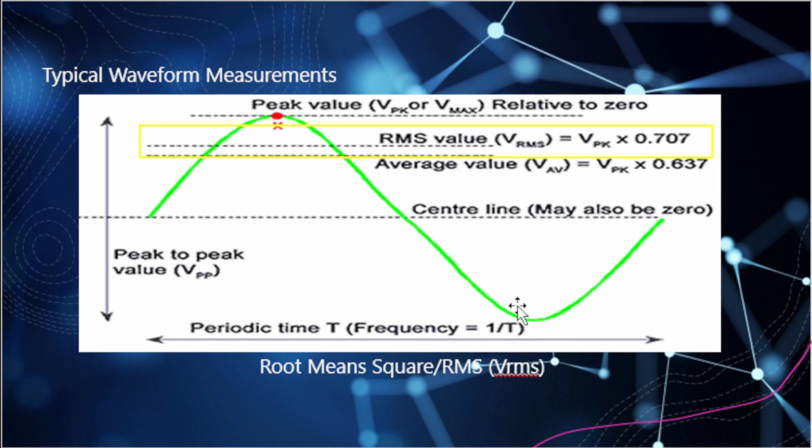Now, what if your guidance, your technical instruction, or your manual doesn't tell you what you should be looking for here? Well, typically, if it's at least saying on your oscilloscope, verify your AC measurement, it is probably referring to a volt peak to peak.